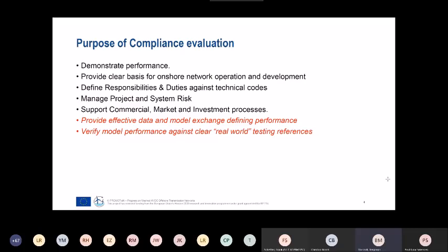completely includes electromagnetic transient phenomena, such as a response to transient overvoltage or a response to the recovery from a fault ride-through event. We approximate that to what we know, which has been the behavior of a synchronous machine in a balanced fault, which is very different to the behavior of a converter.